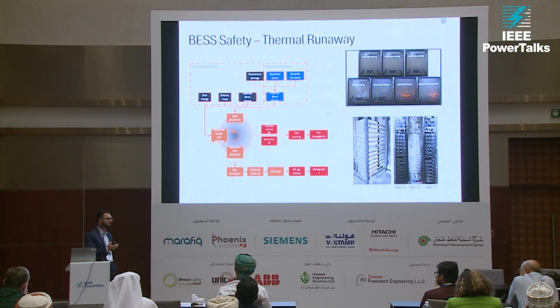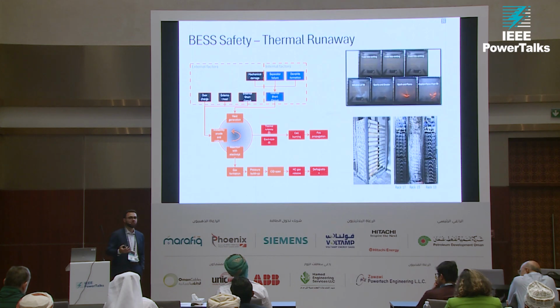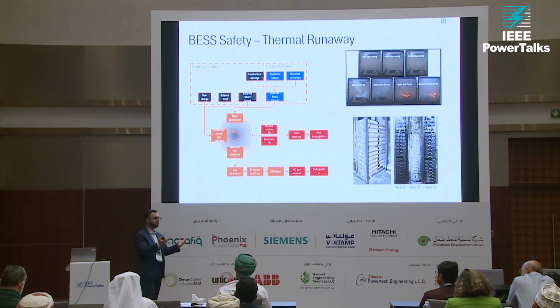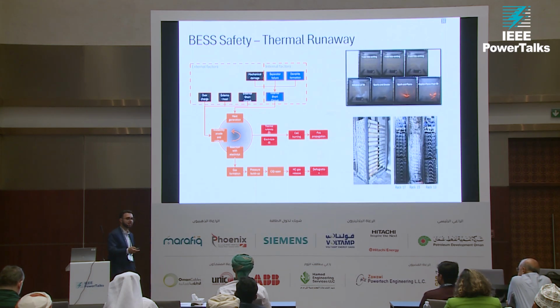So when batteries have a thermal runaway and there's fire, there are gases, and most of these are hydrogen gases or hydrocarbon gases, and those need to find a way to be vented out, because you're creating a hydrogen bomb if you keep those hydrogen gases inside the container, and there's enough volume, and if you introduce oxygen to hydrogen, it burns and it explodes. So a lot of the designs are now around deflagration and how to get rid of those gases safely. There's a lot of innovative designs on how to do that, but we're not going to get into the details right now.